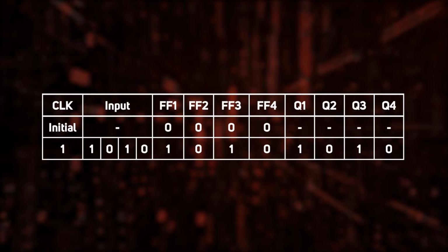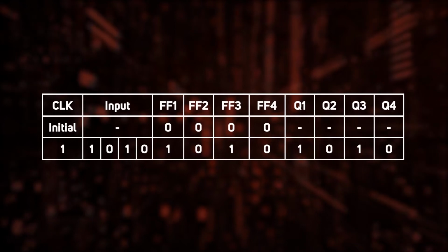The number of clock pulses and the number of bits are not dependent as we had seen in the earlier shift registers. But all good things come with some shortcomings. Here also there is an issue. The design of such circuits will not be as easy as the serial ones. Remember one point, there is an increase in the number of input and output pins, whereas SISO and SIPO were satisfied with either one input or output pin. In PIPO, we need n inputs and n outputs for an n-bit data word to be loaded and shifted in the register.